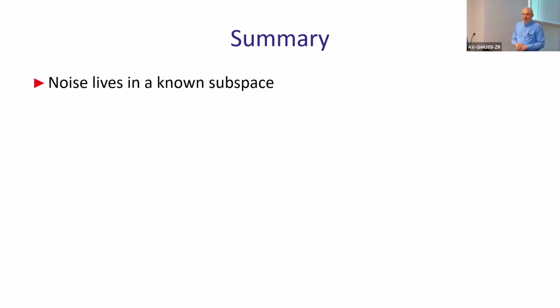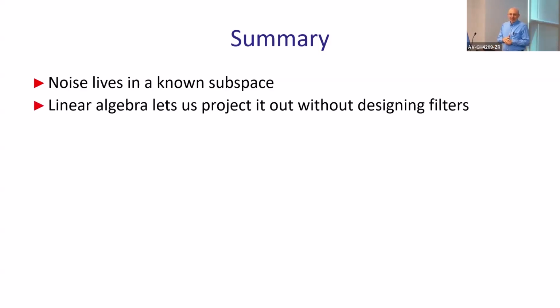Okay, so to summarize what we've seen here, how you deal with different kinds of problems like that. Noise lives in a known subspace and the signal is in a very complicated subspace. Then you can use just basic linear algebra, without designing any kind of filters, to remove that noise if you know the properties of that noise. This is important. You need to know exactly what subspace this noise lives in to clean up that subspace completely from your signal. Otherwise, it will not work. If you don't know anything about your noise, that kind of technique will not help you. You need some sort of filtering of another kind.